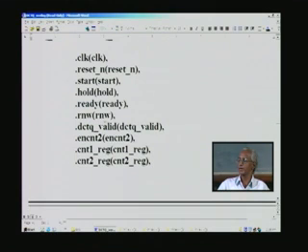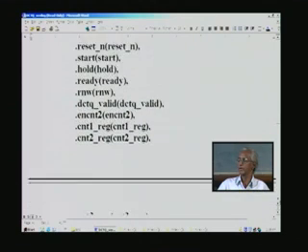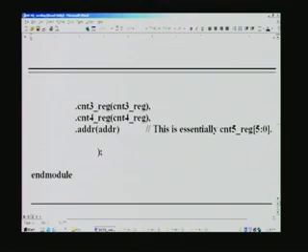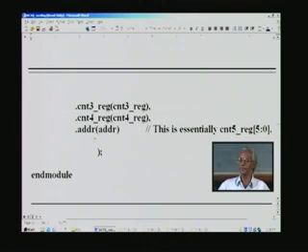We have already seen R and W, and these are all the outputs generated by the controller, and different counters, and the enable counter 2 as well as enable partial product register, and different registers are all there. This is counter 5, or we can rather take it as the address register, providing the DCT quotient address. And this is the end of the top design module.